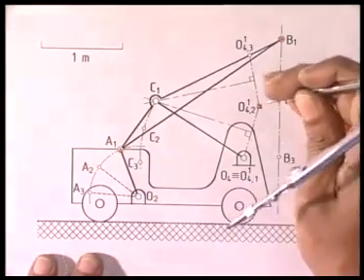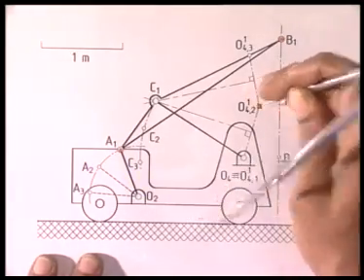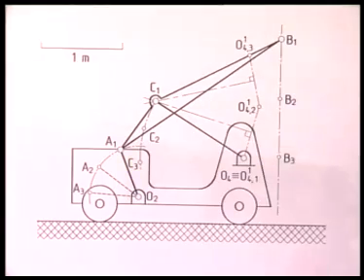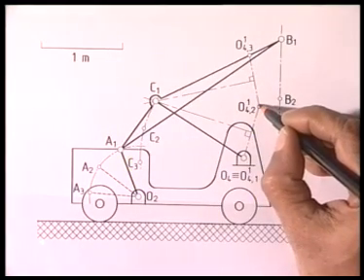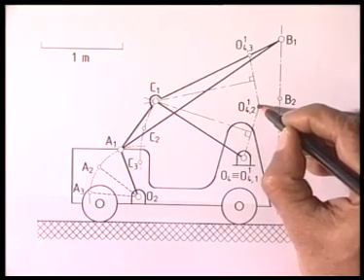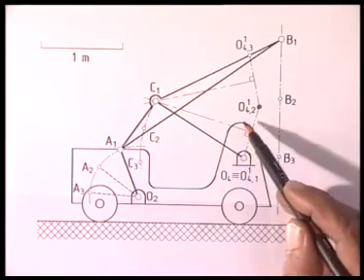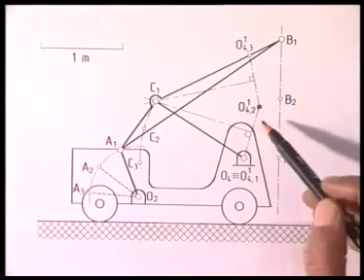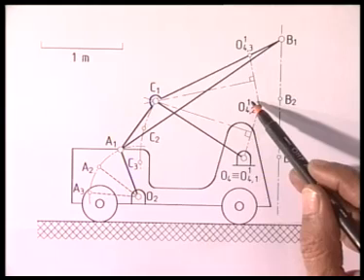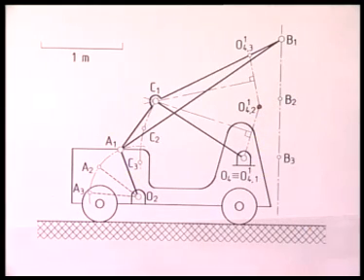by piercing on this tracing paper and mark this point as O4 2, 1, because it is the second position of O4 inverted onto the first position. Following the same logic, I also obtain the inverted position of the third configuration. That is, on the tracing paper, I mark